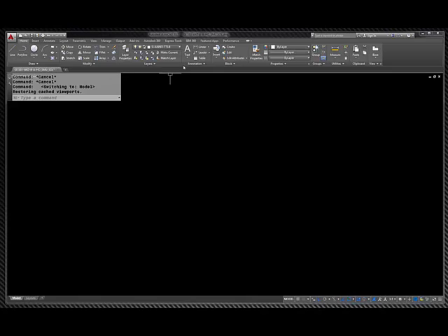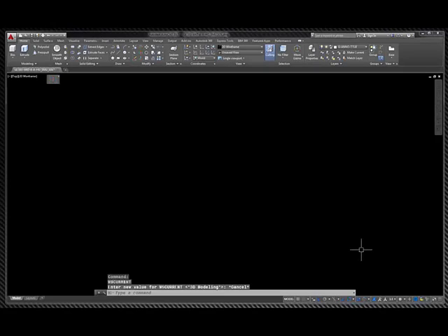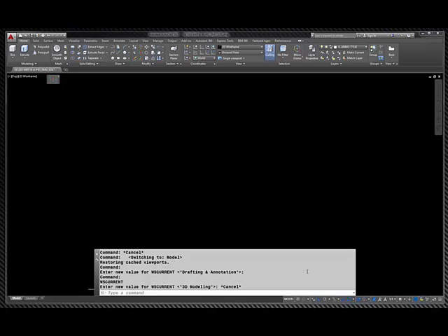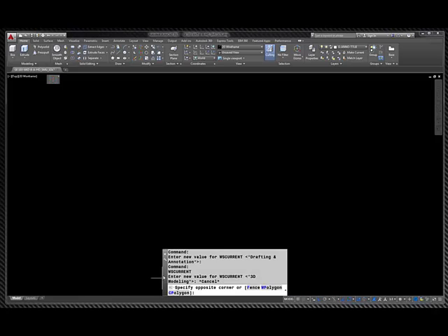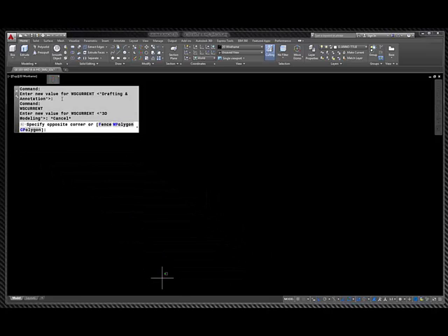First of all, we need to set up our 3D modeling toolbar, ribbon bar up here. So we are going to go down here to the workspace switching, and I'm going to click on that. I get a choice of annotated drafting, which we have here, 3D basics and 3D modeling. I'm going to go to the 3D modeling tab. Click on that. And I am going to keep my command line for you so you can keep track of the commands that we're going to do.